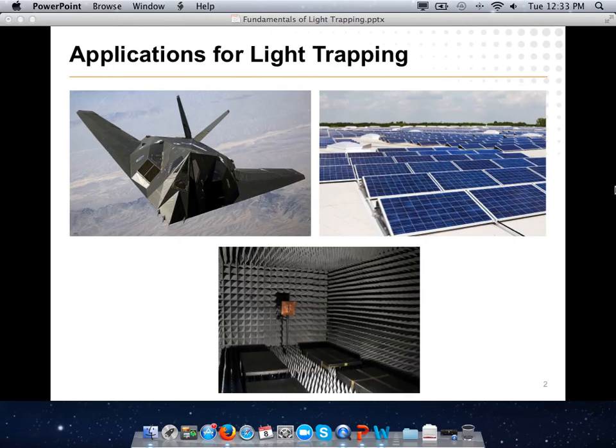Because when I measure the directivity of an antenna, any reflections off stray objects will screw up that measurement. So they have this big metal chamber, and you can't really see it, but there are these little cone foamy things poking out of the wall, and they're designed to minimize echo. Energy will come in, interact with the antenna and scatter away, and without that foam, it would bounce off the walls again and come back to the antenna and screw up the reading.